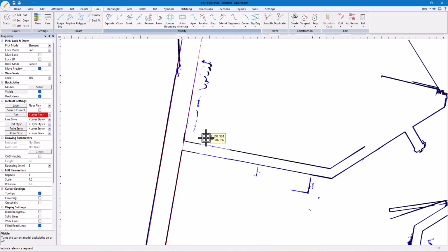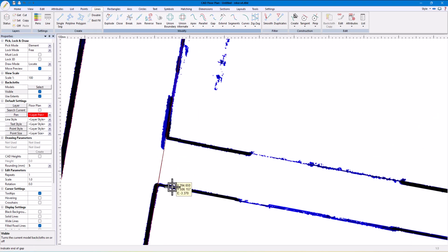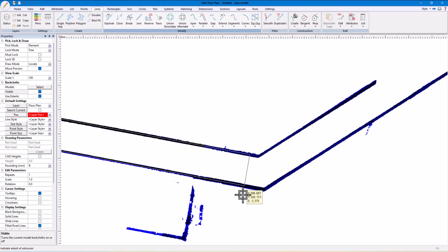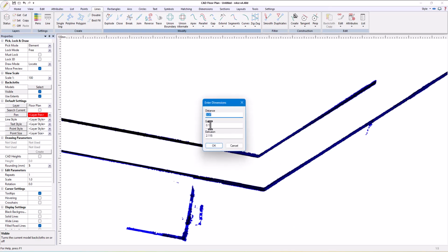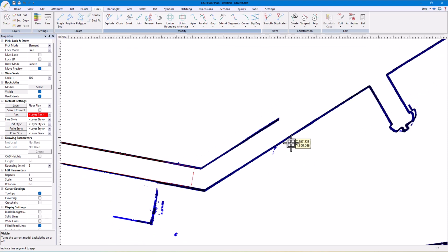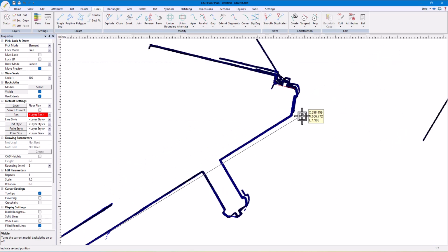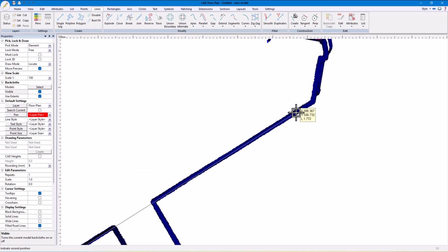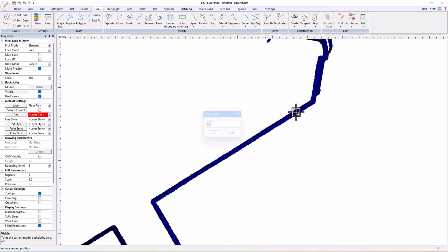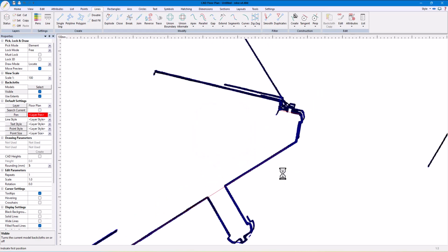The other wall will be started as any normal extrusion, but we will deliberately make it slightly short. We will draw in a partial line segment for the wall that's at an angle and then parallel over to get the back of the wall. Now we can use standard extend and merge functions to complete the join of the wall segments.